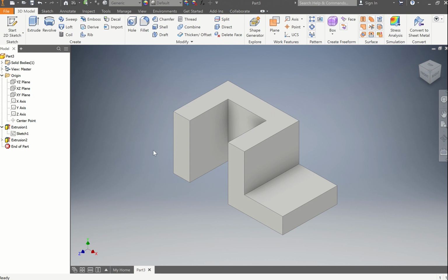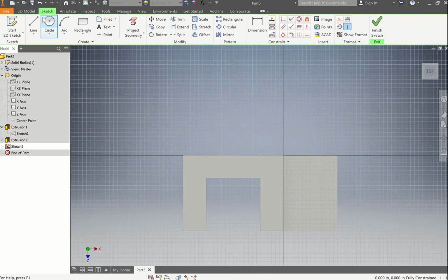And then we are going to create this hole. So just click this planar face and click create sketch. You can just draw a circle somewhere in the area. All right, and then I'm going to hit escape to exit out of that command. Now I'll add the dimensions. So the radius, you always want to try to add your diameter or radius dimensions first. The diameter is 0.75, enter. Then we go from here to here, which is also 0.75.